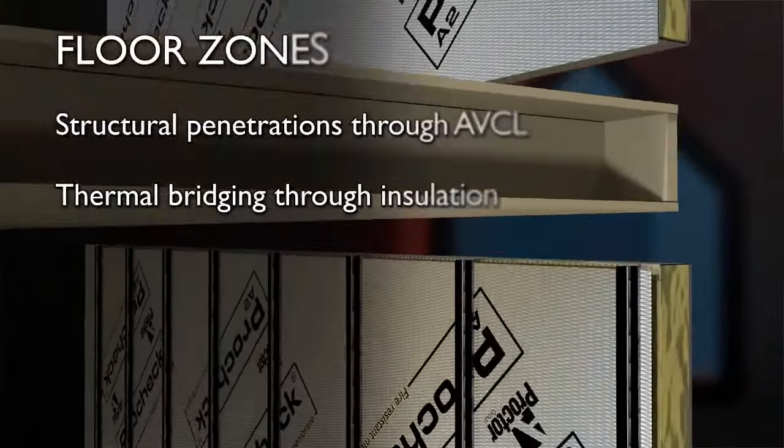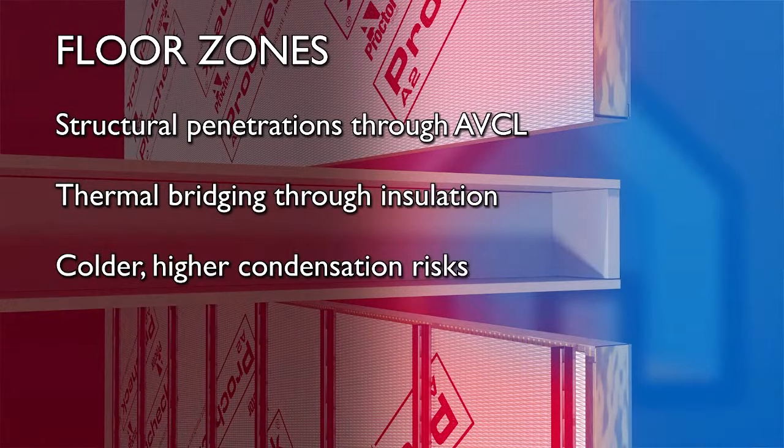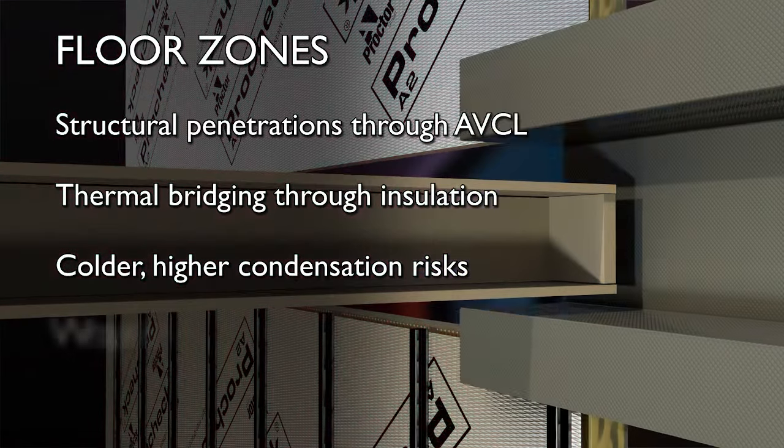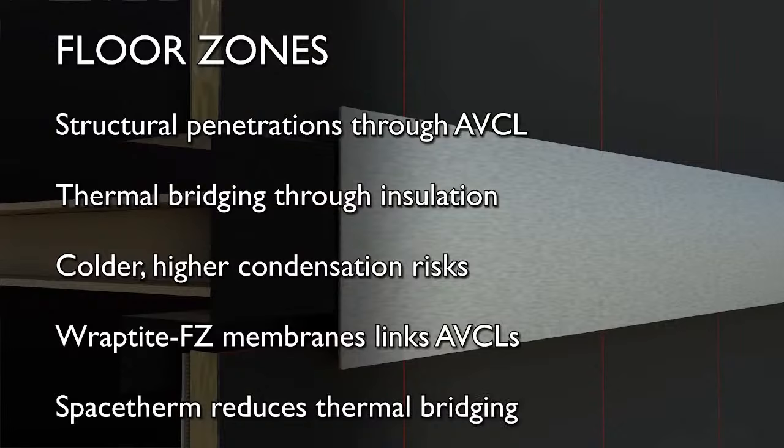Lastly, floor zones and other areas where the building structure intersects the air and vapour tight layer must be considered. In these areas, it's also common for the structure to penetrate through insulation layers, leading to thermal bridging in relatively colder and more condensation-prone conditions. Products such as our Wrap-Tight FZ Floor Zone air barrier can provide a useful additional tool to link the airtight layer above and below the floor zone, while our SpaceTherm aerogel insulation can help reduce the thermal bridging effects.